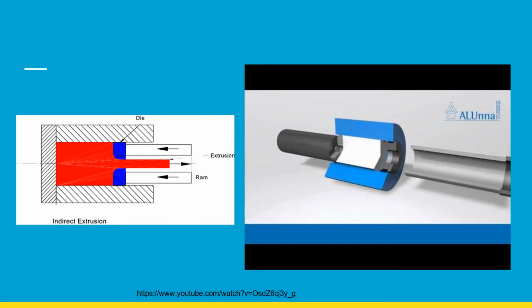The advantage of indirect extrusion is that there is reduced friction in the billet, which helps in increasing the speed and the efficiency of the manufactured product and extruder machine. No heat is formed due to friction in the process of indirect extrusion. The extruded product does not crack, and there is less wear and tear of the machine. The extruded material might comprise some impurities, hence the extruded product has to be finished or chemically treated before packaging and supply.